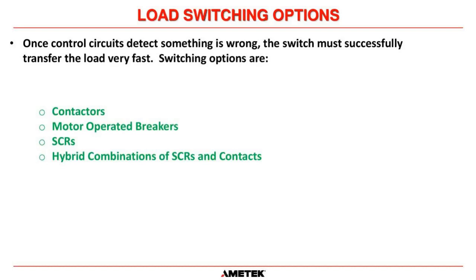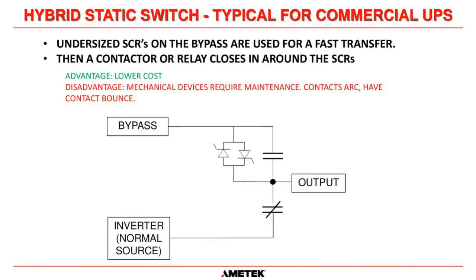Another option is motor-operated breakers. The same thing. They take time to operate and certainly not going to do it in a quarter of a cycle. So SCRs become the preferred means of switching. And then there's some people use a combination of SCRs and contacts as their switch.